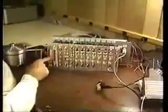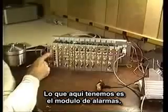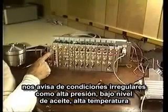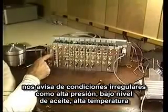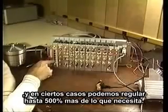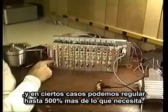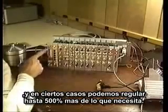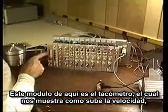Over here we have an alarm module. This module will give us an overspeed trip if the tach goes too high, if we have high pressure, low oil, or high temperature. And in some cases we put a jar switch on there so that, like the Indy 500, that is a requirement. This module here is our tachometer module.